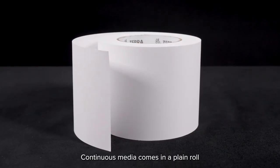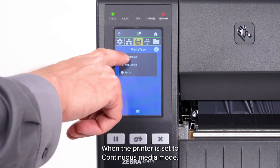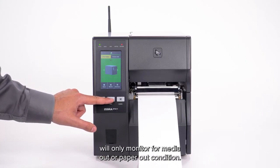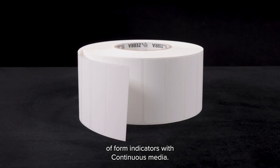Continuous media comes in a plain roll that does not have any indication or separation or gap. When the printer is set to continuous media mode, the media sensor does not detect label length but will only monitor for a media out or paper out condition. While in this mode, there will not be any top of form indicators with continuous media.